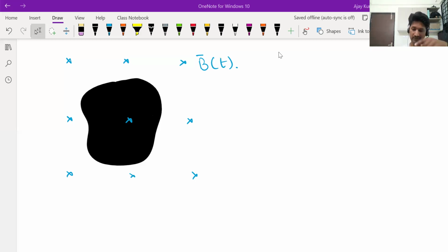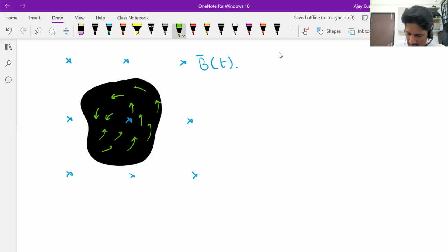We know that. So as a result, in this plate, charges will start moving around everywhere because the induced electric field is produced everywhere, right? So electrons everywhere will start moving. So randomly you will see currents flowing at different points, or you can say at all points of this conductor. There's no well-defined path for the charges to flow. This current is what you call eddy current.